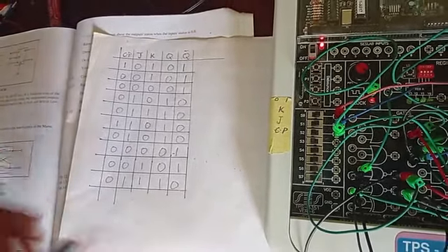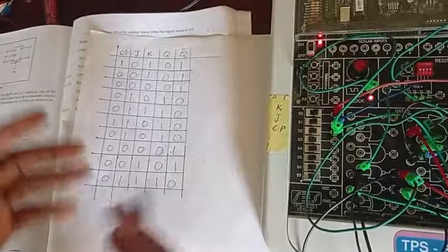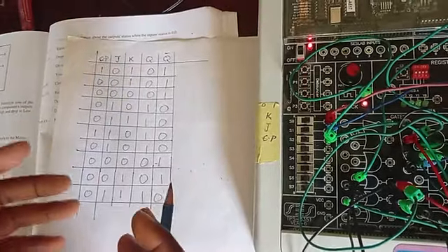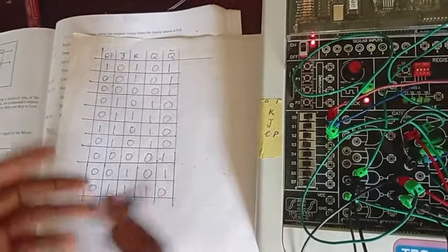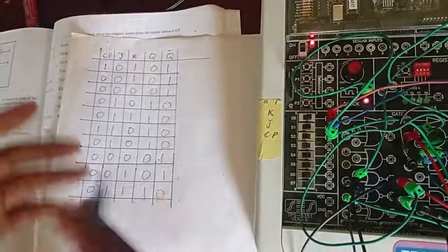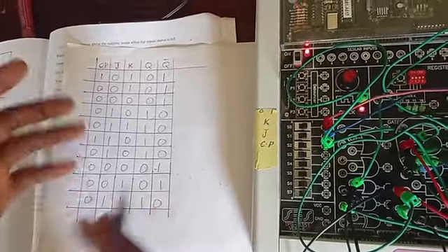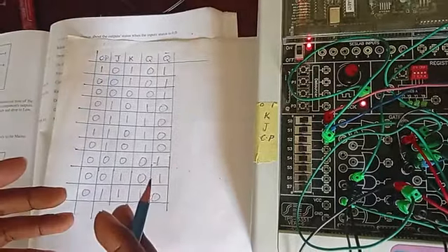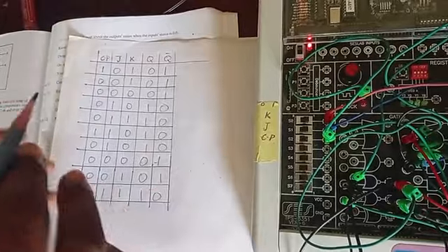Sometimes people use it for their changeover, so that when you have 2 inputs at the same time, it's going to pick one. So you can use it for changeover, so that if we have both NEPA and the gen, it's going to pick one, even if we switch on the 2 at the same time.